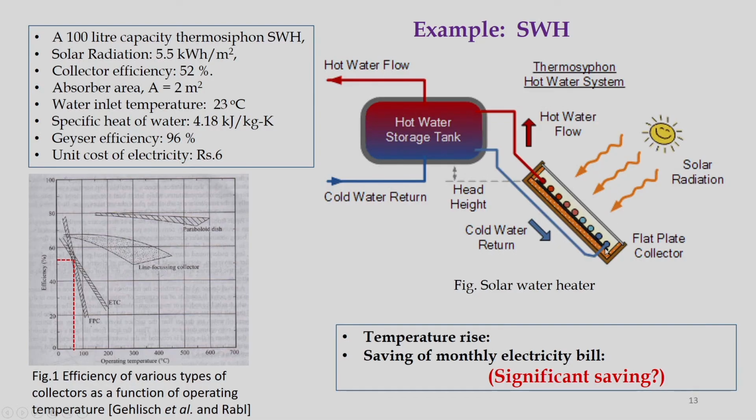So, in passive water heating systems, due to this temperature difference, there will be density difference, and because of that mass movement of the fluid will be there, and this is the reason why this cold fluid is introduced, and then when heat is supplied from the sun, this heated fluid will go up and occupy the top portion of this reservoir or storage, and then finally this can be collected based on the applications.